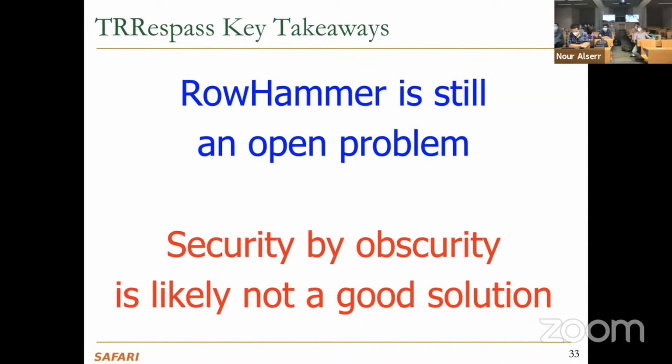Yeah. So a question first is, you said the required refresh rate has gone up. Is that just because cells have gone closer and they're more noisy? So now by hammering a single row, you can go and access more rows at once? That's right, exactly. Basically, cells are closer, things are more leaky, and noise is higher, and also cells are smaller at the same time. As a result, the number of activations you can do to induce a single bit flip has reduced significantly.